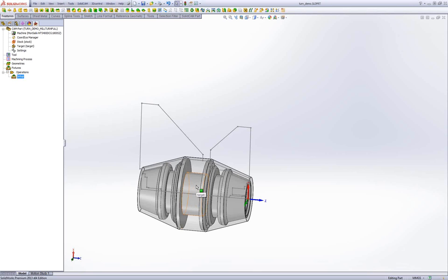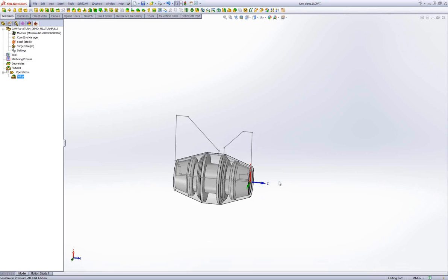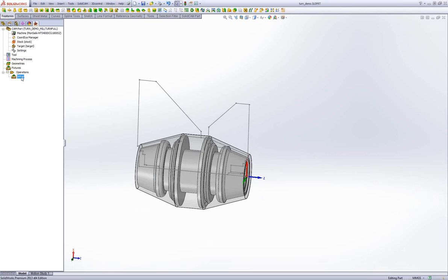Maybe you start working directly on the sub spindle, or between working on main and working on sub spindle, you don't use any machine control. You manually take the part and put it on the back spindle. So the software doesn't know where to position the part. This is the reason that we define here the position of the part with fixture on main and also on back.